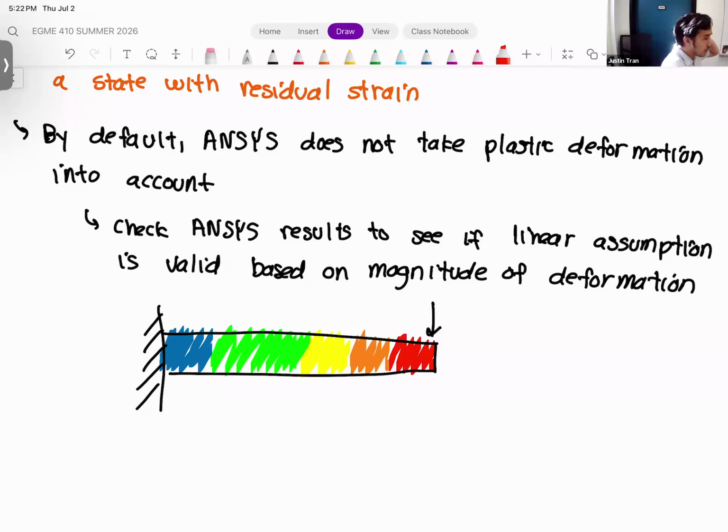That would be the deformation plot, which is what we expect. Without putting any numbers on this, if we have a beam that we know is fixed on the left-hand side and we're applying a force on the right, we expect the deformation to be highest around where we're applying the force. So from the color deformation, there's nothing alarming. That's exactly what we expect, which is very similar to our plate with the hole.